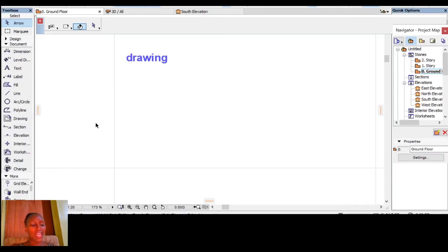So this navigator helps you a lot when you want to create folders or you want to copy or drag or drop views depending on your particular purpose. The navigator also lets you access views and layouts from external Archicad files and place them in the layout book of your current project. Maybe you want to import an outside project. You will use the navigator.